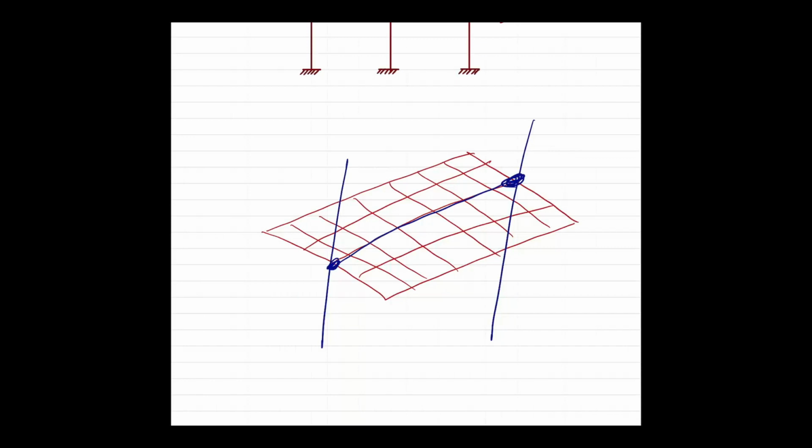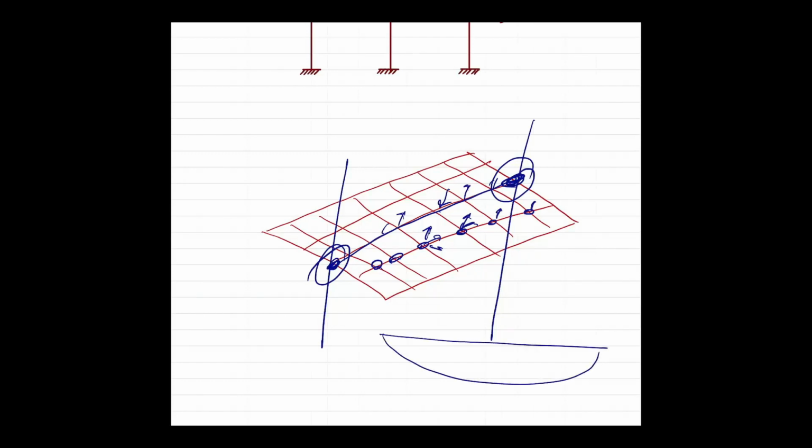Well, let's look at the logic. When you write a structural analysis program, the degrees of freedom are here, just these two ends. Whereas the node on the slab, on the shell, you have here, here, alright, x, y, z, x, y, z. If there is nothing that is used to restrain the profile of the beam to the degree of freedom of your slab, you don't connect the beam with the slab, right?